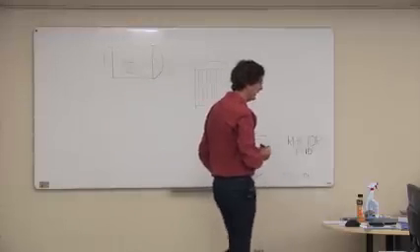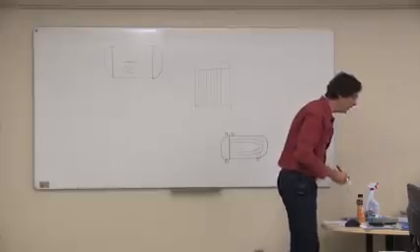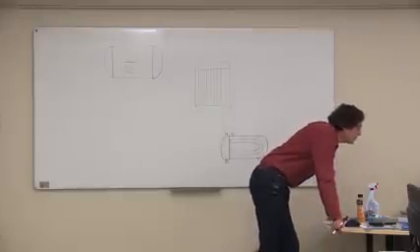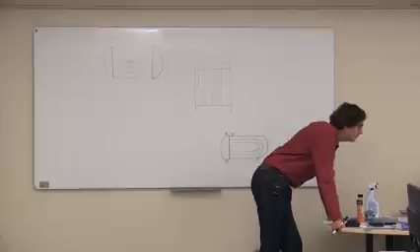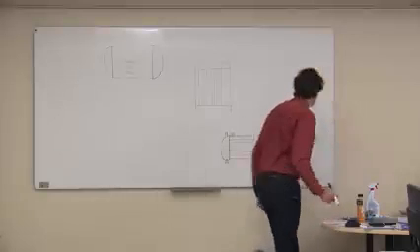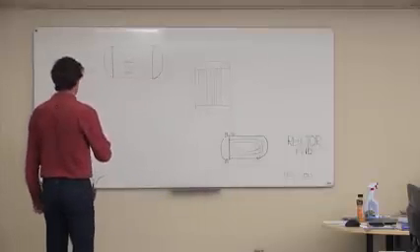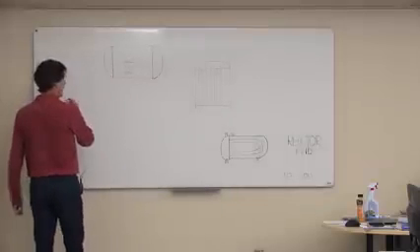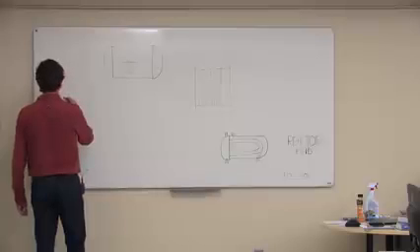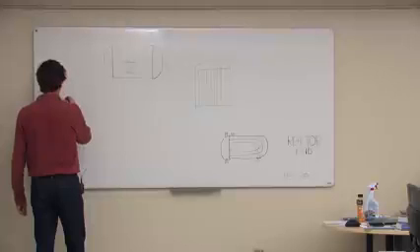Okay, so that's that. The other piece of equipment that we've got to get on there is, looks like we have a cooler going into the reactor for now. So let's draw that. We might not actually have space on here to do that, but we'll try and get it on there. This may be a case where we have to push it onto one of the other P&IDs. I will put it here.